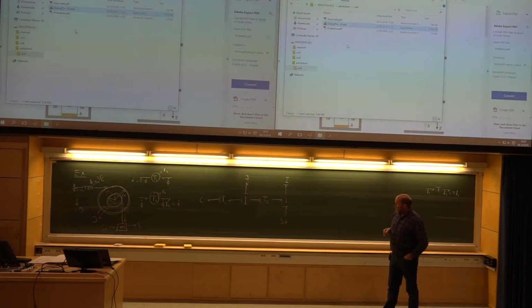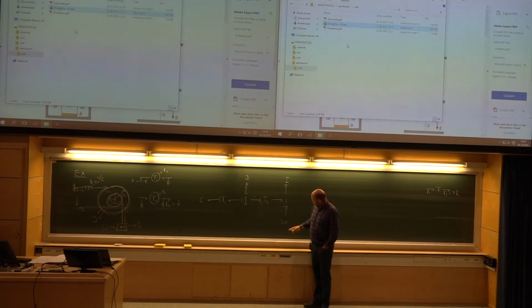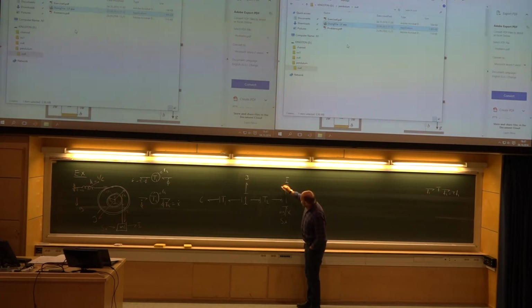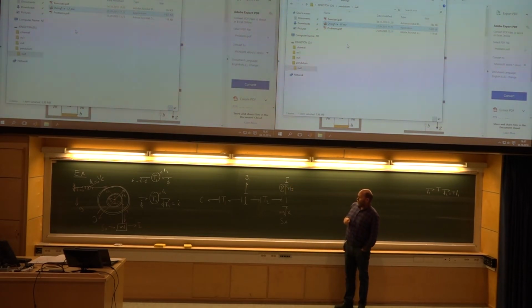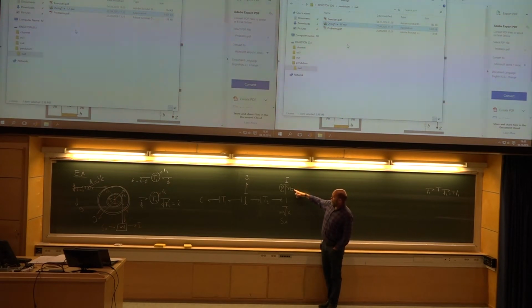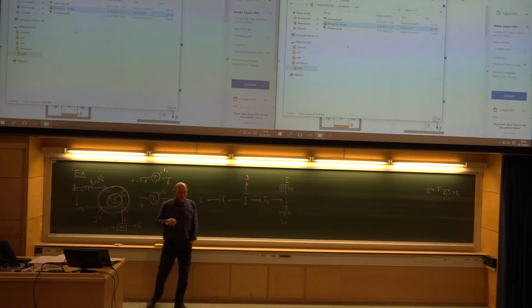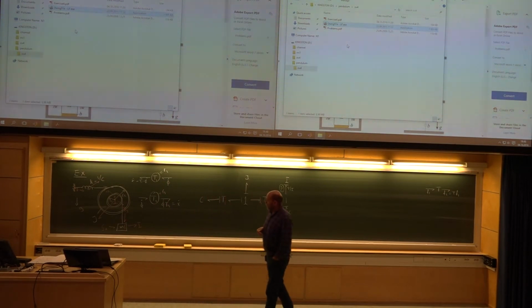So now let's try to annotate this bond graph. Here we have the gravity, mg, and the flow, I don't care. This I element is on the correct form, so I can write p dot on one side, and on the other side, p over I. So here's a convenient thing. I have the mass m, that's I. The j, that's the rotational mass here, the rotational inertia for the wheel.